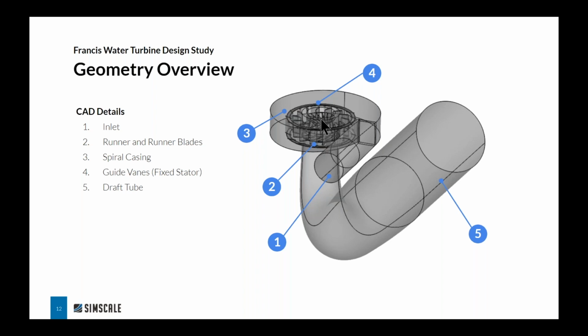So once the water moves through the runners, it comes down through the back, and this is known as a draft tube. So this is where the water exits out, and we try to minimize any losses and equalize the pressure with the design of this draft tube.